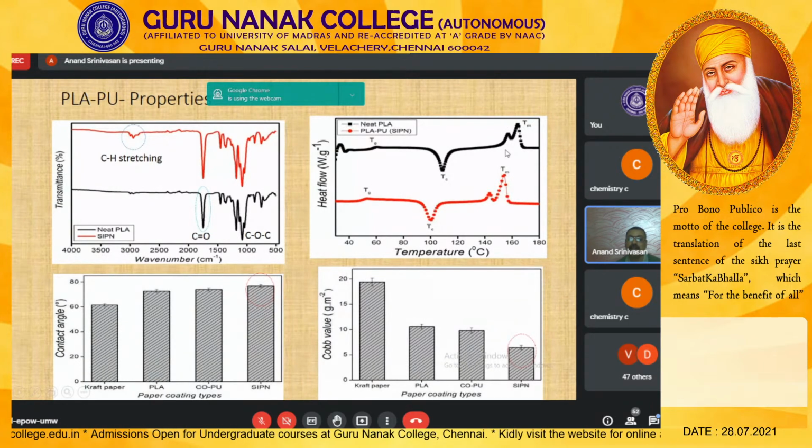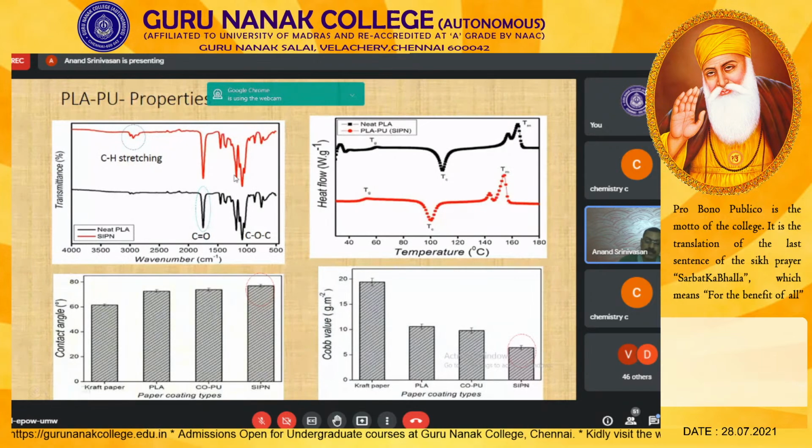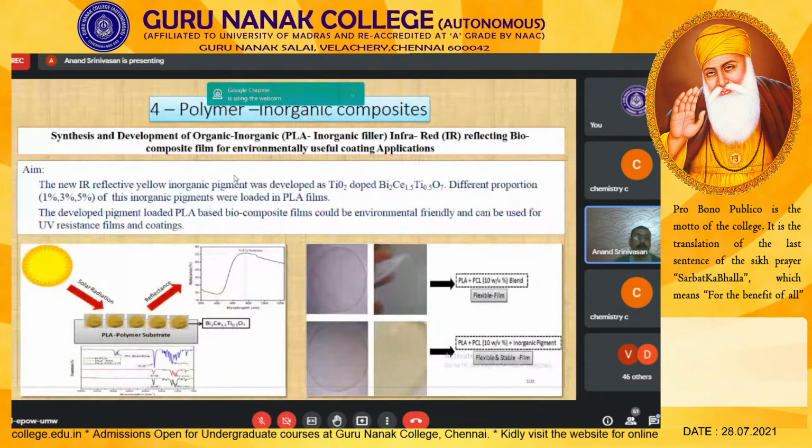Meaning is that this polymorphism is responsible for offering barrier property. So we are not compromising the barrier property or the polymorphism when PLA is mixed with the PCL. Okay, so that is another important thing, and we were able to understand the semi-interpenetrating network by IR. Again, there is a shift of vibration frequency which indicates the interpenetrating form. And this work, we are really very happy to share this work.